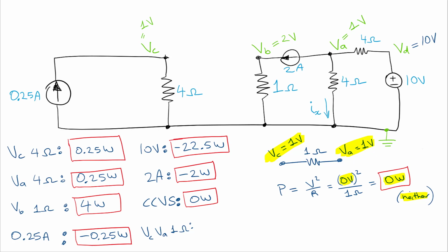Quite interesting. And we actually see 2 independent circuits, one on the left and one on the right. And there can be no current flowing through this branch here, right? Because this is an open circuit, so the current through there is 0. So we just have the current flowing around this way, and then whatever the current is doing on the right-hand side. Okay, that's quite an interesting result, a very unusual circuit.